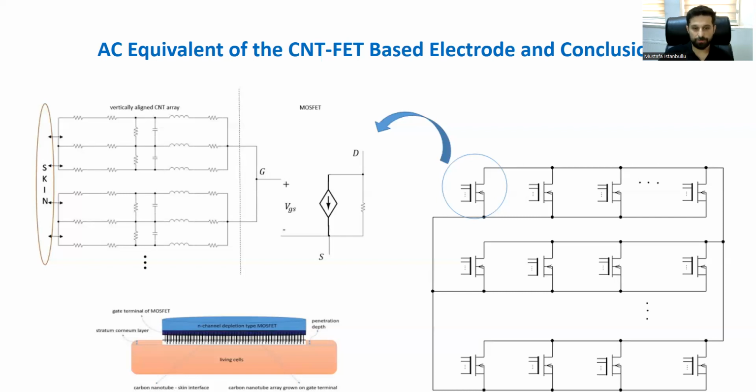The measured electrophysiological signals on the gate terminal control the drain current. At low frequencies, for example, 1 to 5 Hz, the gate terminal of the transistor exhibits an impedance that is too high to affect the measured biopotential signal.